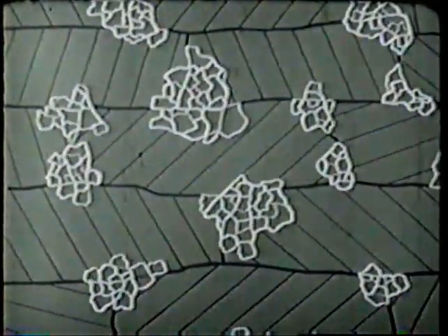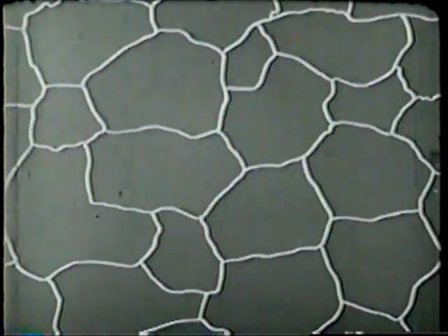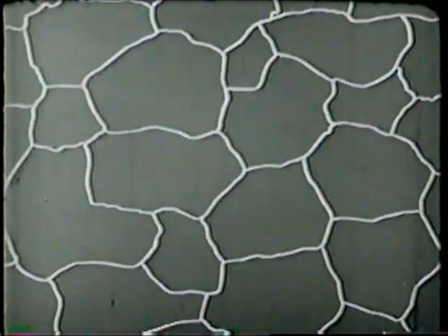As the metal is heated to recrystallization temperature and above, the nuclei of new grains are formed from the fragments and crushed particles of the original grains. These nuclei may merge with other fractured particles or with portions of the original grains, growing into new stress-free grains. The metal is now annealed and in a soft condition for further forming.